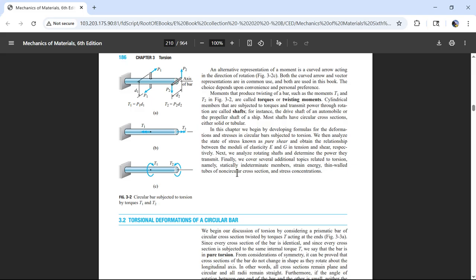So if you generate 1 psi of axial compression in a tank, that number isn't astronomically small, because that tank will yield at 50,000 psi. So if you had 50,000 people on one side and 50,000 people on the other side, all pushing 100 pounds, with 100 inches squared of cross-sectional steel on the tank, you could get it to permanently deform. So there you go, right to the yield.